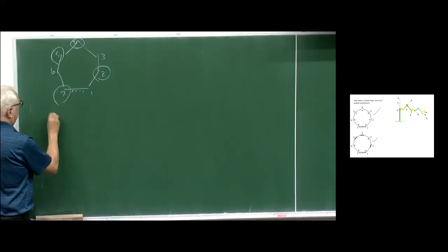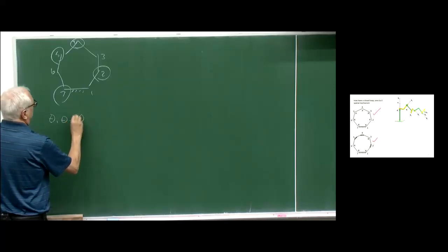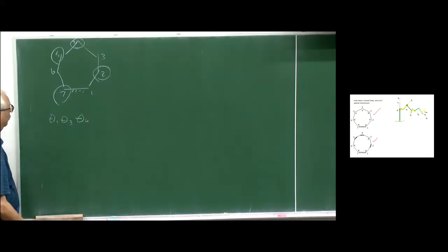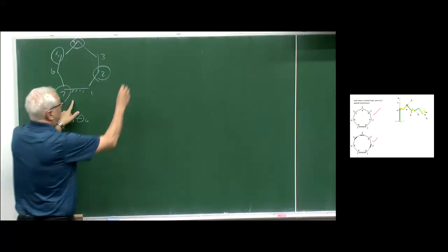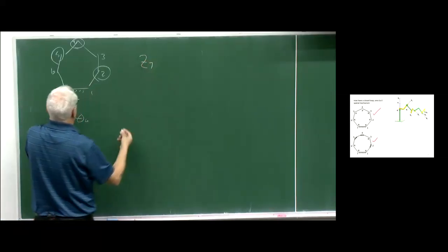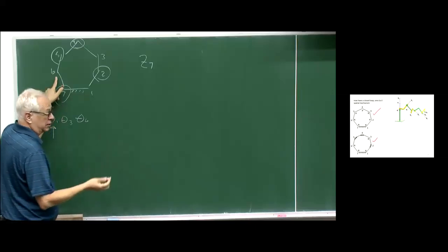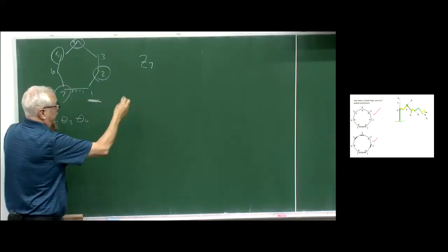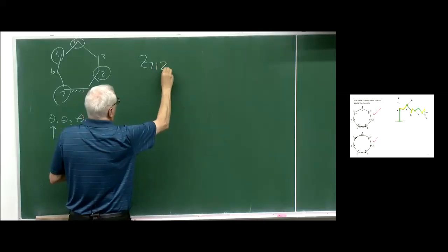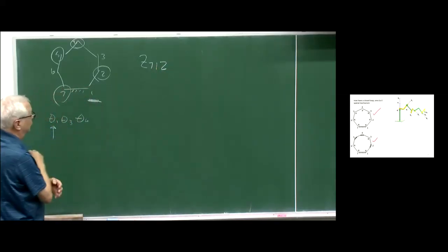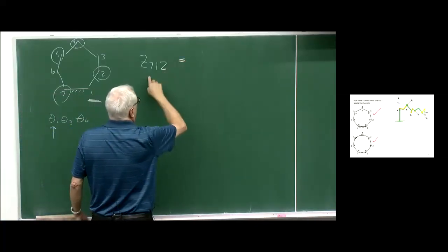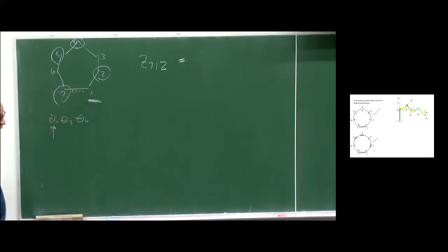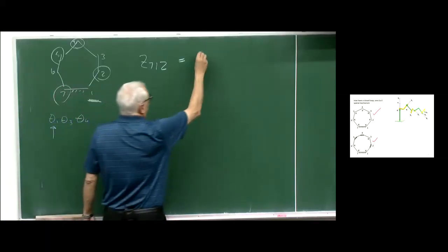So the 3 joint angles that we need to get are theta 1, theta 3, and theta 6. It's just a matter of who we want to go for first. If I go for theta 1 first, then I'm going to look at the cosine law that'll get me that. So it's going to be Z, and I'll say 7 is okay. I don't want to put 6, right? I'm looking for 1, so it's okay to put 1 in the equation. It's okay to put 2. Oh boy, I don't want to put 3, right? Because I don't want theta 3 in the equation. So I stop and say, well, to get a fundamental equation, I'd have to have 5 subscripts, and I only got 3, so I know it's a subsidiary cosine law.